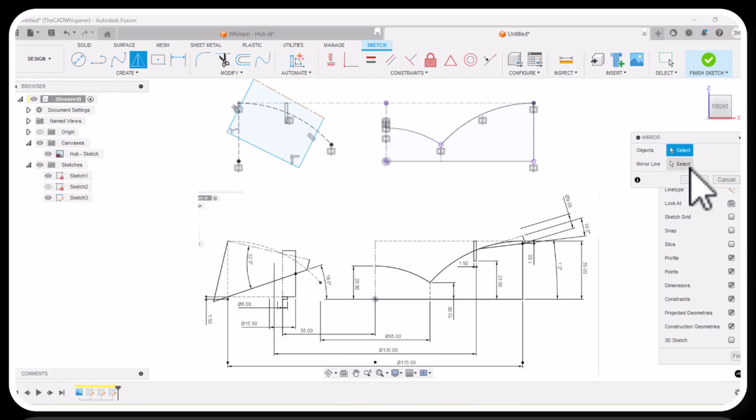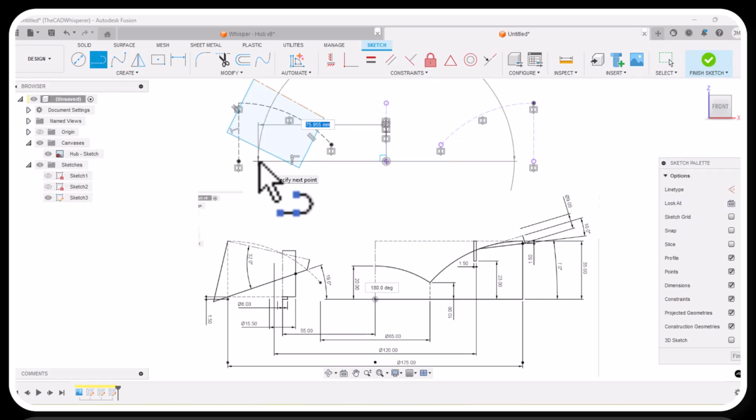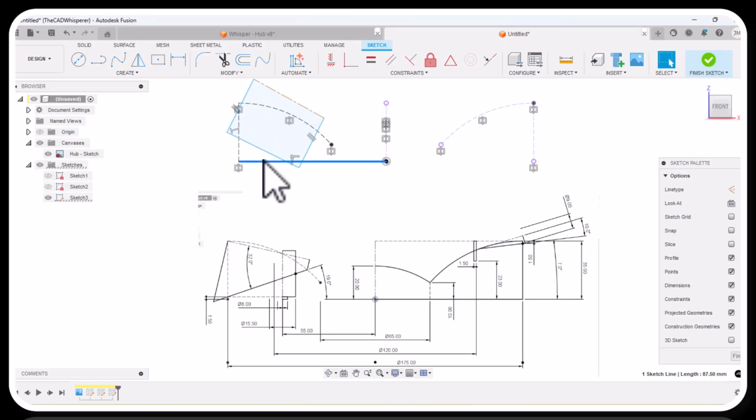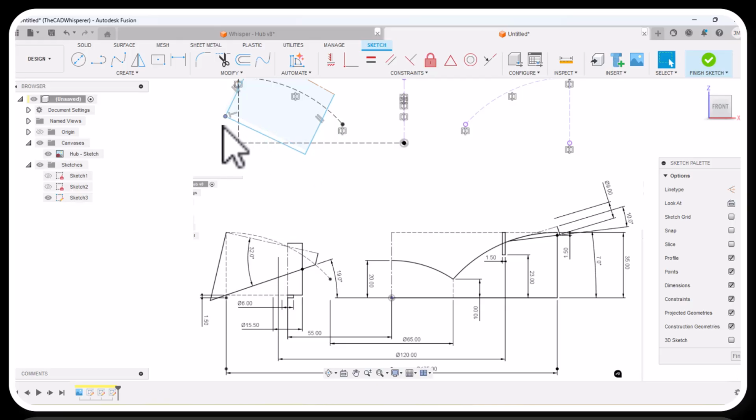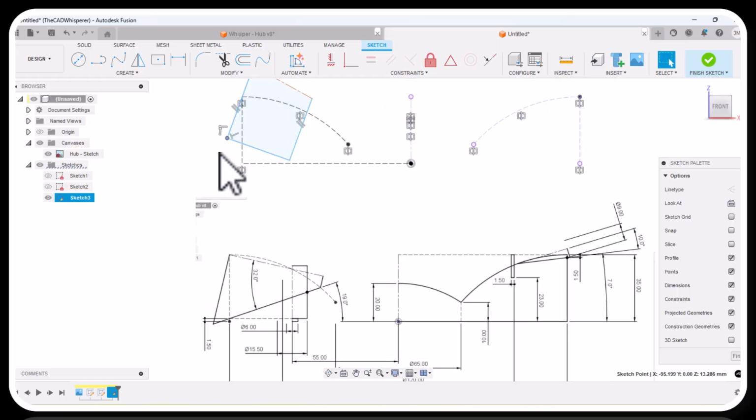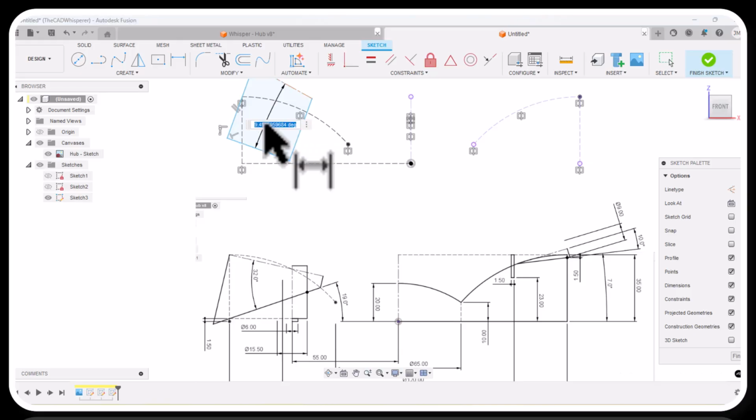Let's just draw a construction line in here, construction line over here. And we mirrored this line, so we can just draw it over to that point. And I will change this to a construction line, X on the keyboard. And then I need to put in that 19. And actually, this line is going the wrong way entirely. And I might have some trouble getting the angle that I want. I actually drew the rectangle in here, perhaps not the way I want. Let's try putting in this 32. So I'll dimension between here and here, and let's try doing that as 32.